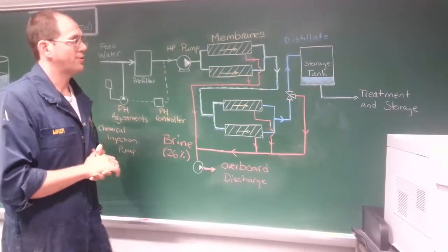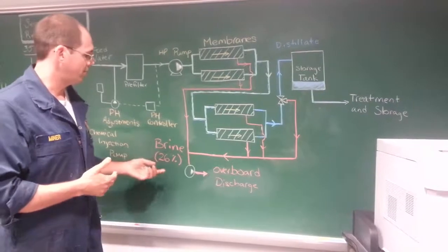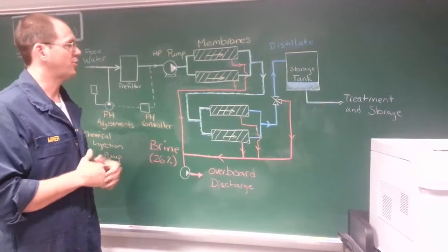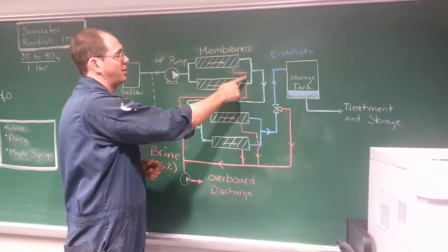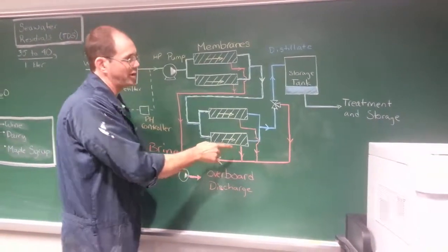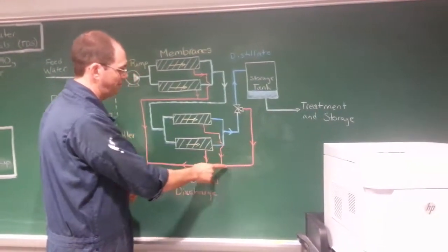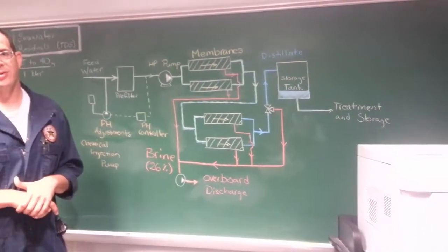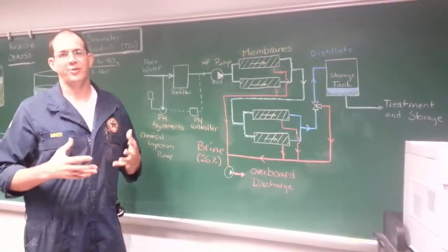And as mentioned earlier, because of the total dissolved solids, we have to pull what's called brine, which is typically about 26% salt within the water, so a heavy concentration of salt water. That comes out through brine discharge lines, as annotated here, and as well if the distillate gets contaminated, which you can see here at the three-way valve, it goes back into a common line and is eventually sent overboard. And Ms. Geisbauer will cover this as it applies to specific ship systems.